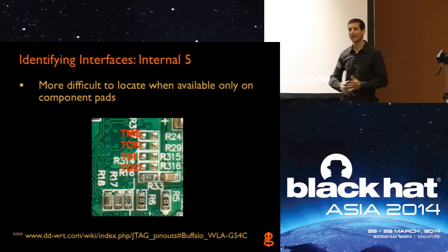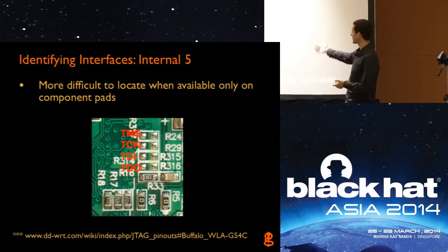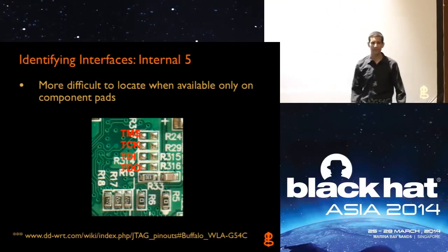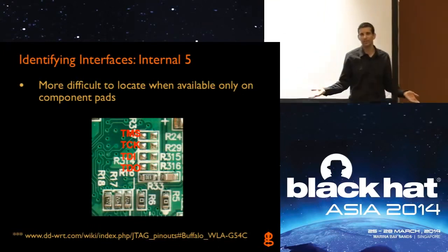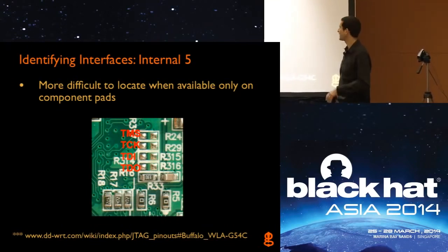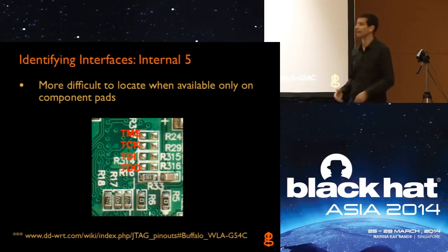When you look at the board, you don't know which components are there or missing intentionally, or which ones are there to obfuscate an interface. You just don't know. But once you find out that those are the interface pins, that's not going to change for any revision of the board. So it's totally just security through obscurity, and it only takes one person to find that and release it on a website for everybody. But it does make it way harder. And that's where the JTAGulator comes in.